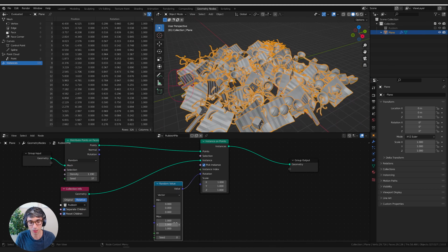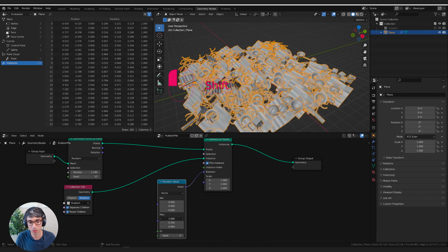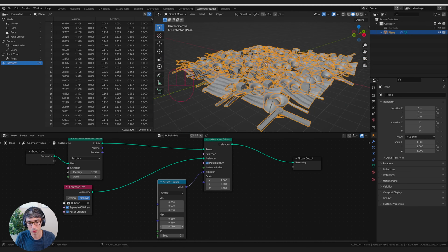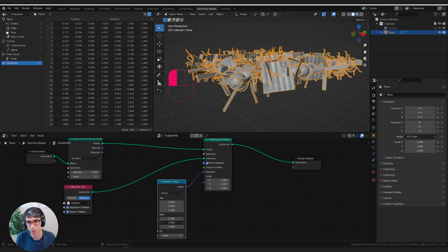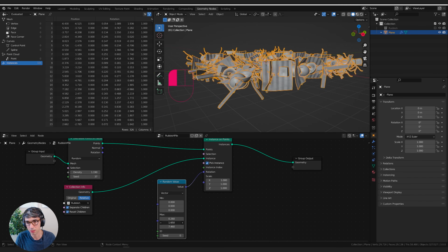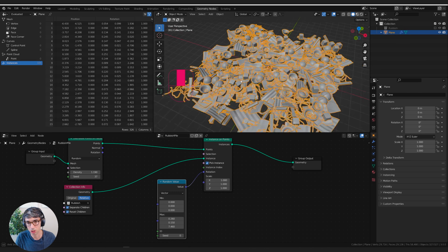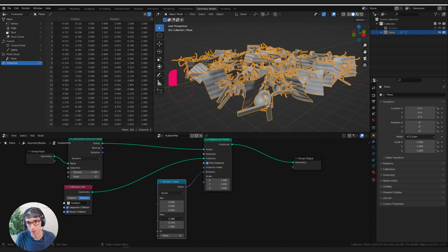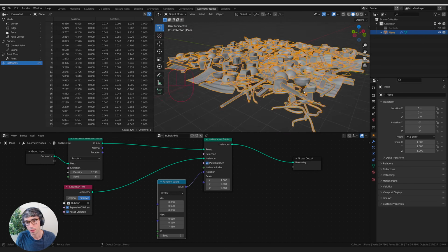Now we can adjust these a little bit. If we take the minimum and maximum, we can turn down some of these if we don't want it to be quite so crazy. What's going to look good? We can turn this one right up because that rotation looks good. This one I want to be a little careful of because it doesn't look quite good, so I might turn this one up just a little bit. I'm holding down Shift and dragging, and that allows me to do a finer number tuning. You can move them slower. And this one as well, we don't want to go too nuts on, so I'll keep these a bit lower. And there we go. That looks pretty good.